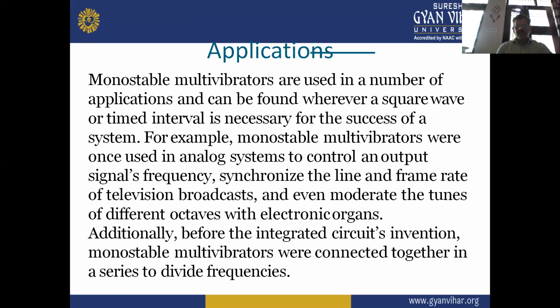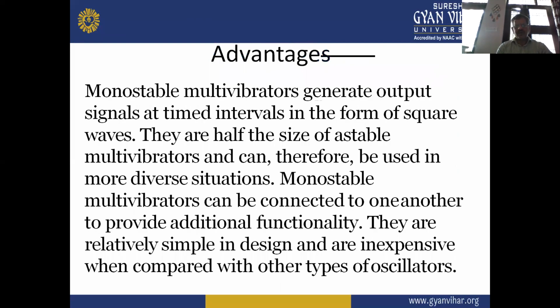For example, monostable multivibrators were once used in analog systems to control output signal frequency, synchronize the line and frame rate of television broadcasts, and even modulate the tunes of different octaves in electronic organs. Additionally, before the invention of the integrated circuit, monostable multivibrators were connected together in series to divide frequencies. So these are some applications.